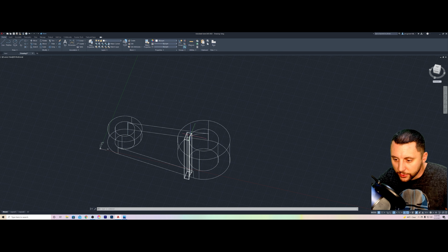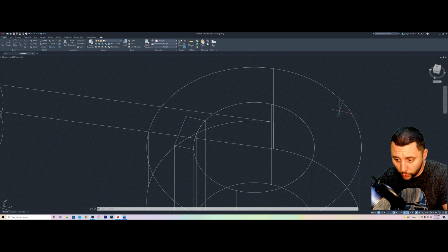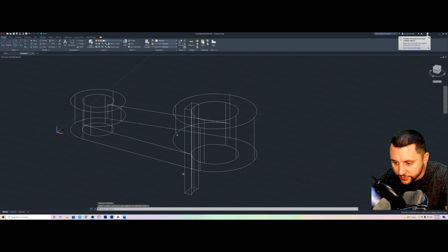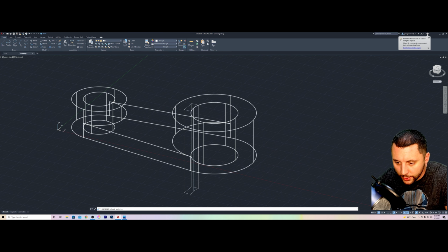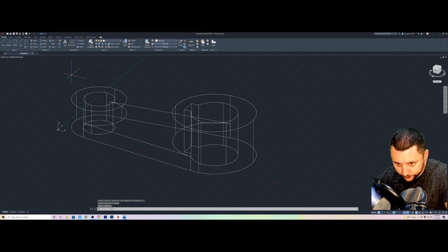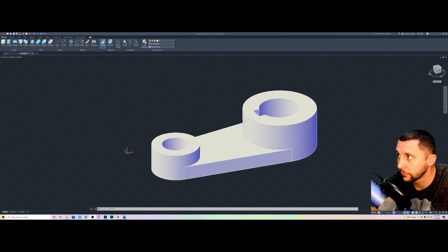And then you would have trimmed right here and you would have had this keyway open, and that would have been a join rather than just the circle extruded down and subtracted away from the big one. But it works either way. So I'm going to do a subtract now. Remember that I just went through the bottom. Doesn't matter how far you go as long as you go all the way through. Subtract from the main model, enter, small model, enter. And on conceptual, you'll see that that works out, okay?